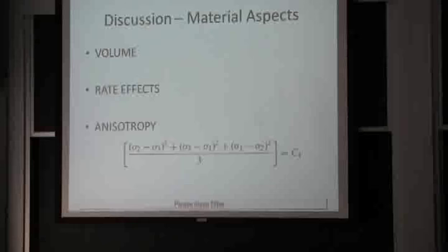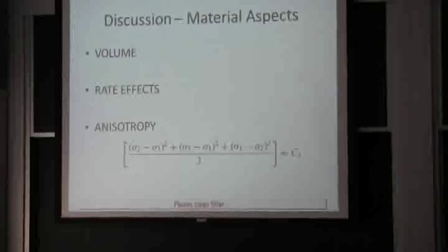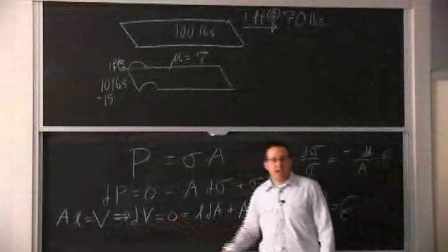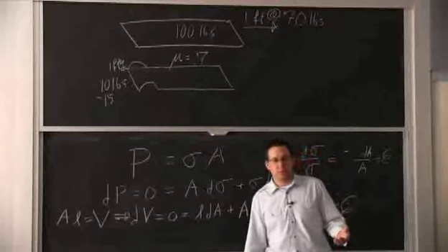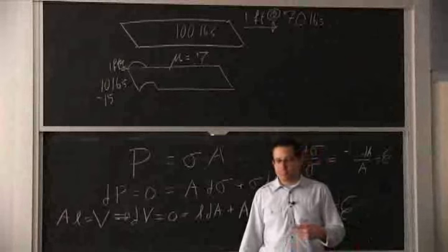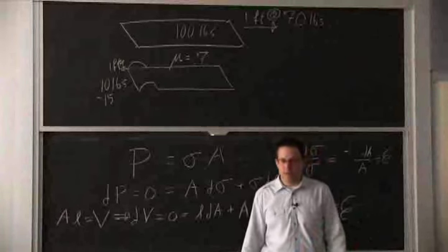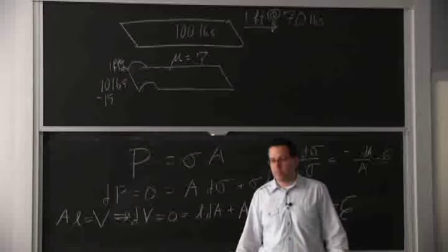So to wrap up that part on deformation, one thing I hope you realize is if we deform, we don't lose atoms and we don't create them. So our volume stays the same. And a lot of times if we were to quiz you, that's something we will quiz you on, because it helps you add an equation. We've done it right here. It helps you add an equation to determine the solution. So metal and most plastic will not change significantly in volume when you change their shape.